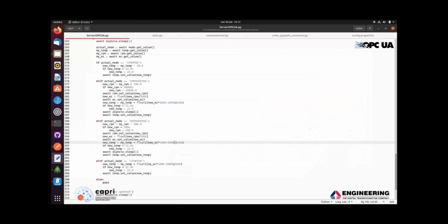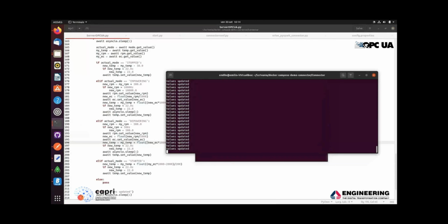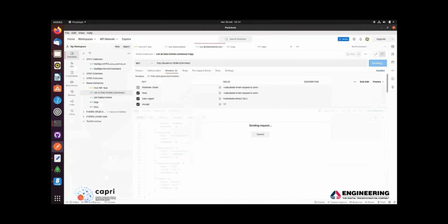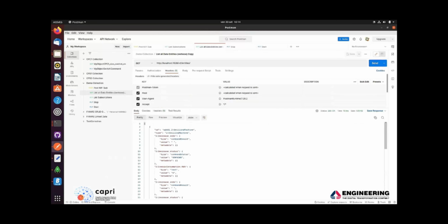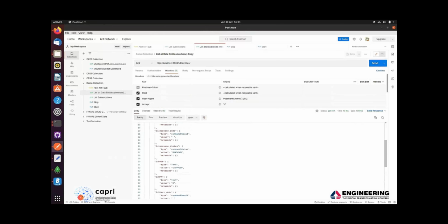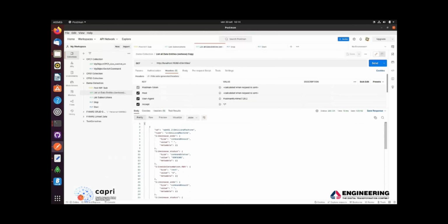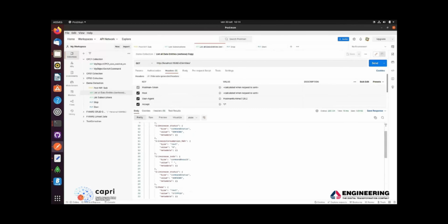Before starting the machine again, let's introduce the FiWare OPC-UA IoT agent. This tool connects to a running OPC-UA server and maps entities, attributes, and commands from this server to the Orion Context Broker. Now, let's start the agent. Upon starting, the mapping is done and now the agent starts transmitting attribute updates to the Context Broker. The communication is also bidirectional. By calling commands from Orion, the agent is able to execute them on the OPC-UA server.